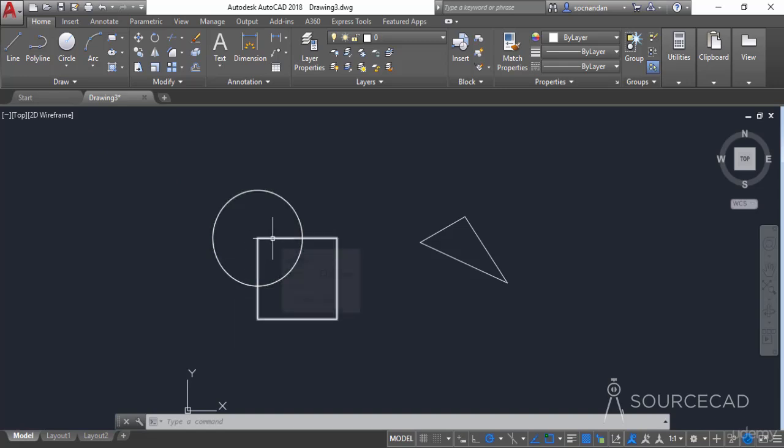Now here in this case, we have a simple polyline. Let's convert this one also into a region. So I'll select the region tool, click on this and press enter. We again have a new region here. Now I'll convert this object into a region. In this case, you can see that we can select it separately.